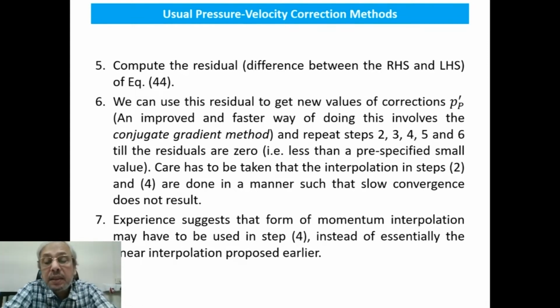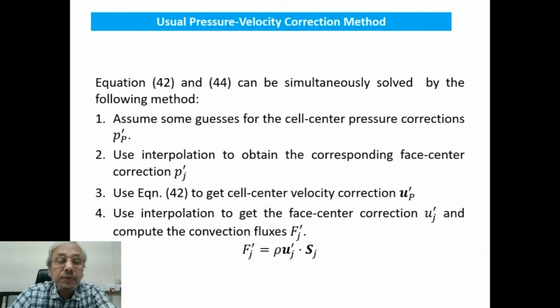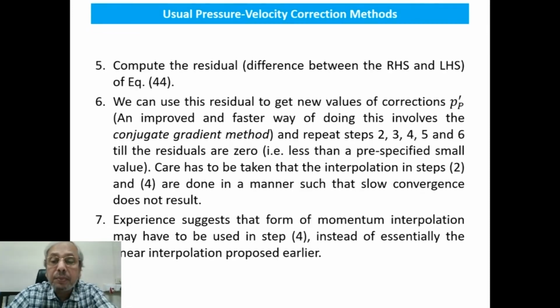Again, let us look at step 2 and step 4. Experience suggests that a form of momentum interpolation may have to be used in step 4 instead of essentially linear interpolation. So in step 4 we may deploy the momentum interpolation technique.